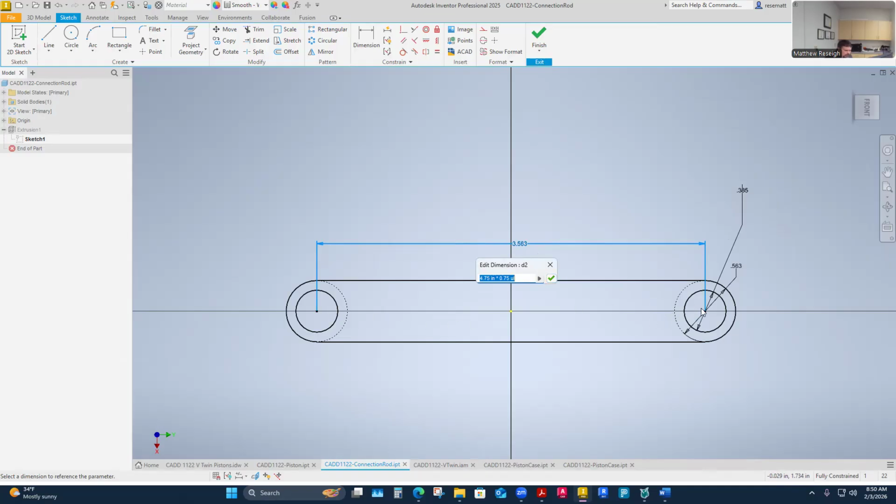If this length was off a little bit, it would be critical in a real operation. For us, we wouldn't notice it, but it might not push my piston as far as the other one potentially. If those dimensions needed to be refined, it might change how far the piston pushes in and out of the bore, the cylinder, which is really critical in an engine. But it's not something we've really analyzed. So I didn't add any tolerance to that, or even the outside radius.